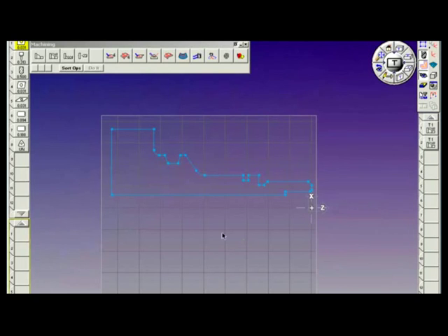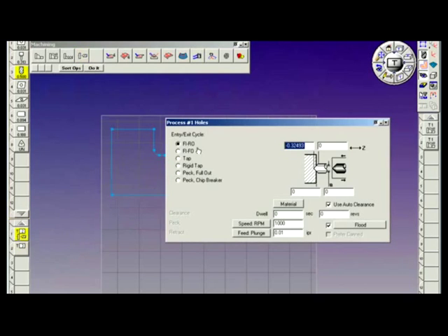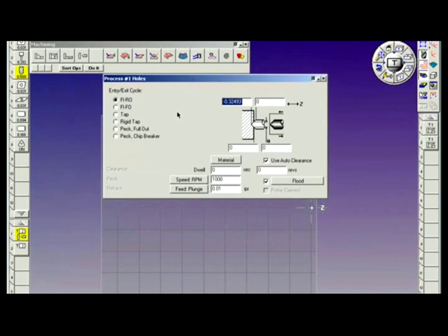What we're going to do now is a multi-tool operation. We're going to spot or center drill and drill a 1/2 inch hole on this part. So I'm going to group the tool number 2 in process tile number 1 and bring down tool number 3, process tile number 2. Combining these two tools will apply them to the same selection as a unit. We'll take our holes process, drop it on process tile number 1, and the cycle options are feed in, rapid out.